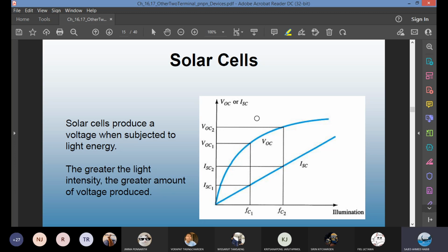But for some countries, especially very far north, the sun angle changes. In different months of the year, the sun angle will be different. Also, the intensity of the light will be different. So if you put a solar cell in a fixed position the whole year, some months you will get good power, some months it is useless. That's why in large solar farms, the solar cells are connected with a rotating motor. Depending on the position of the sun, they track it and move automatically to get a more steady amount of electricity.